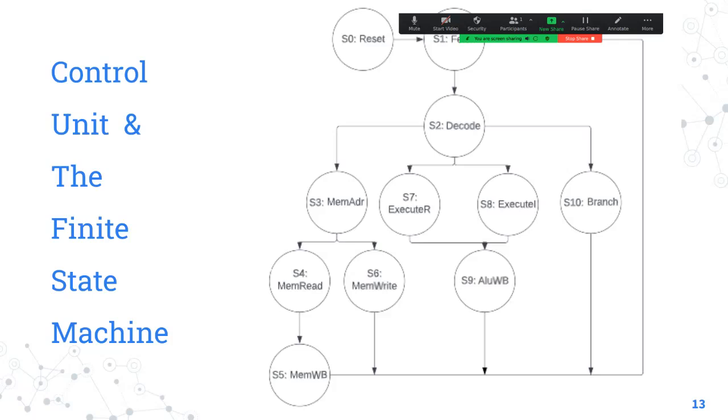But what we realized is that when we keep on reducing the time period, which we can do in Verilog, after some point the output, whatever you see in the display or whatever values are being written to memory and registers, are garbage values. They are not the values that you would expect from the processor working. This is because there are a few stages which require some time before they give you the final correct output.